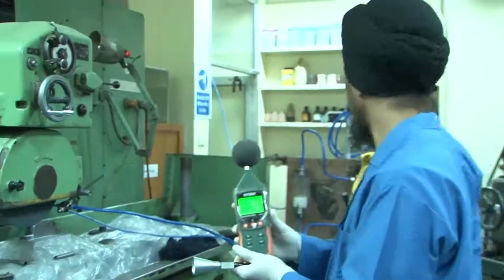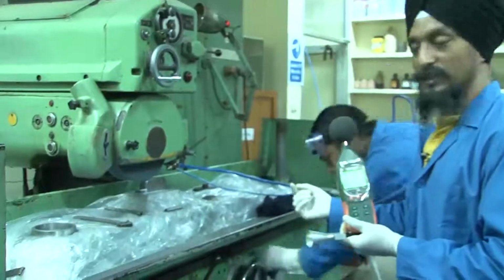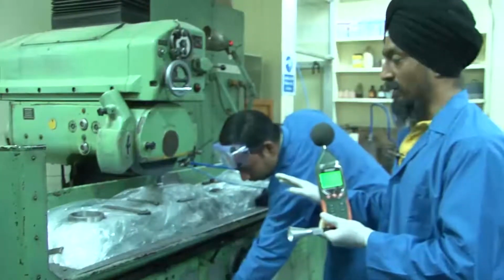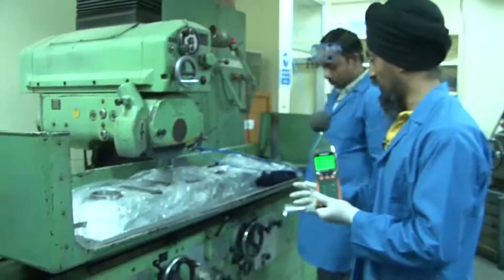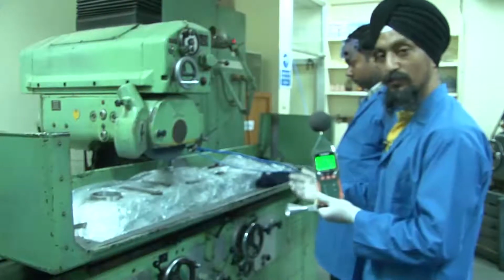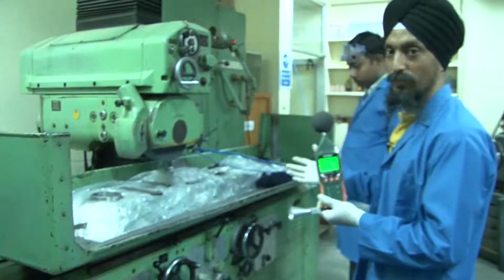Yeah, we can start now. We have given 6 micrometer of depth of cut, and the table speed here is 10 meter per minute. In this machine, the least count for depth of cut is 0.2, that is 2 micrometer here specifically.